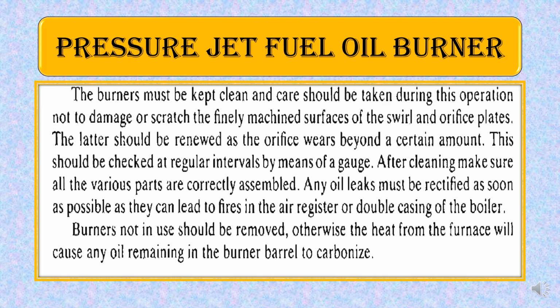The plate should be renewed when you find that the orifice has worn out by a certain amount, because hot heavy fuel oil is continuously passing through it, so erosion will happen and somehow it will be enlarged, so it needs to be replaced. This should be checked at regular intervals by means of a gauge. After cleaning, make sure that all the parts are correctly assembled. When we are doing the maintenance, especially the threads have to be perfectly clean so that it will assemble correctly.